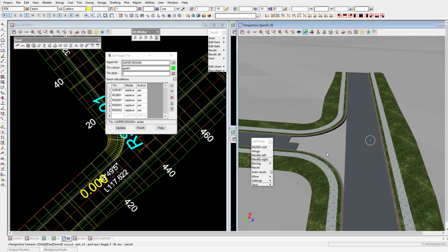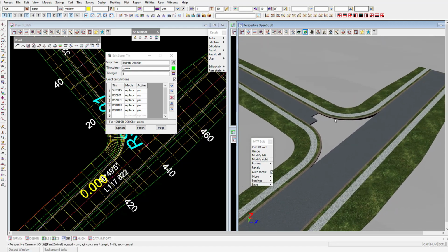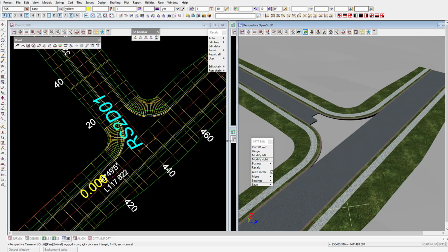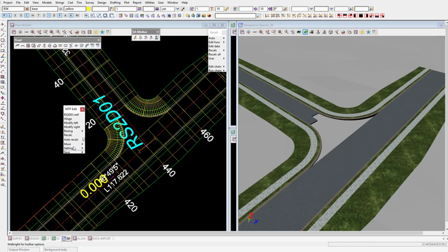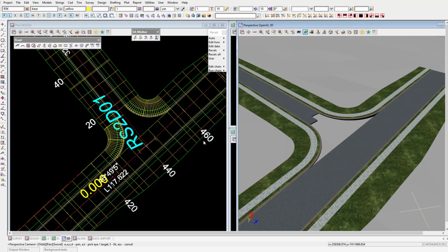is what we've previously done. But because we've done nothing on the right hand side of our curbs, we're not getting that area filled in there. It's just defaulting back to the survey. So a quick way to fill that in is to use a snippet in 12D. So I'll get out of that particular road. So you use a snippet and you fill out the right hand side of each curb.